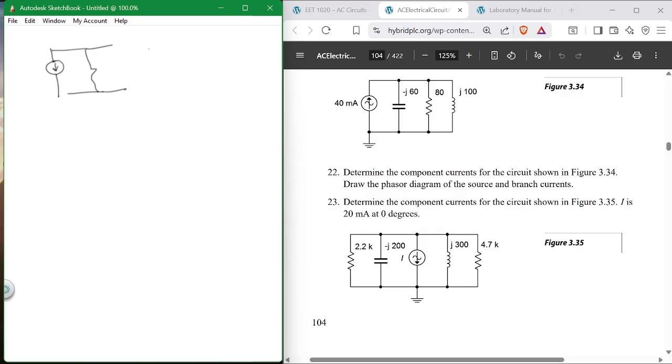Take the 2.2K, move them over to the left, and then turn it into a voltage supply with V here equal to I times R, and then put the resistor up here. So this I and this R become this and this. Why is that?